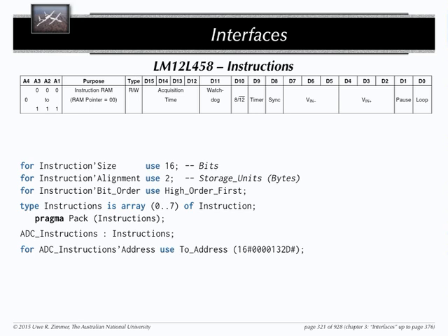If you read your data sheets later on, it will explicitly say this register has to be addressed in full word size. This has to be addressed in half word size. This has to be addressed by a byte load instruction. This has to be explicitly told to the compiler or whatever you use for that one. You control the bit order inside my words, how the thing is supposed to be enumerated.